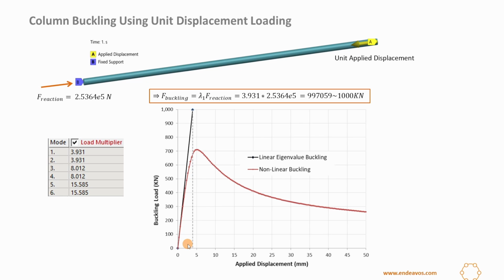To answer this question, we have to really look into the broader context of how this rod is used in a structure. If buckling of this rod can lead to a catastrophic failure of a structure or a system, then we should have sufficient safety margin. In that case, I might use a load factor of 2.